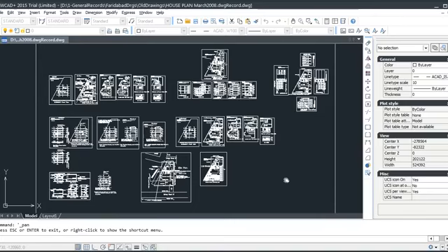Likewise we check all systems, and we prepare the supporting system for the slab. People do it like bullies, or they do something else. Except in 2 or 3% of buildings I've seen, nobody uses the proper system. That system is the real one. That's a very strong system, because of your weight, your load, setting load, material load, and the unbalanced load during pouring, because on one side people are standing, on the other side pouring is going on. There's unequal load, and there can be eccentric loading. Sometimes there can be accidents, and this happens.